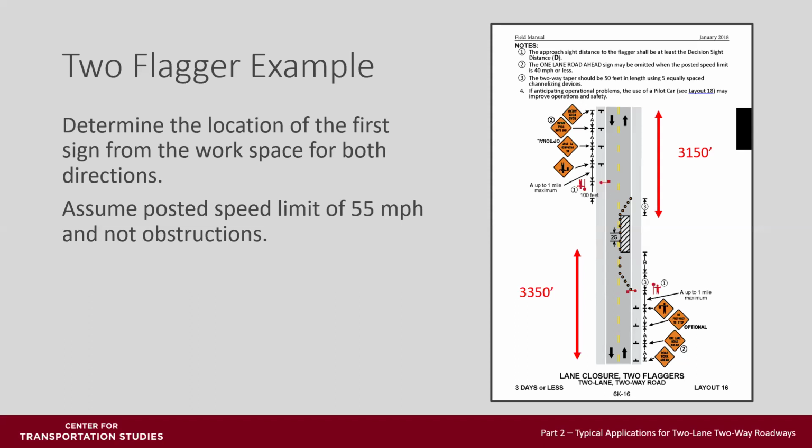There are many ways to measure to determine distances needed, and a readily available system is to count the broken line or skip pavement markings. In Minnesota, these are all at a 50-foot cycle, so counting 15 skips would give you 750-foot sign spacing.